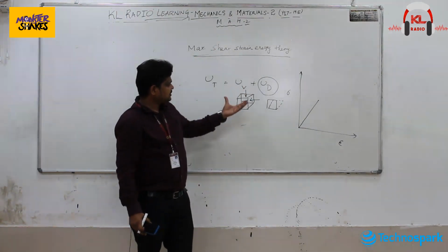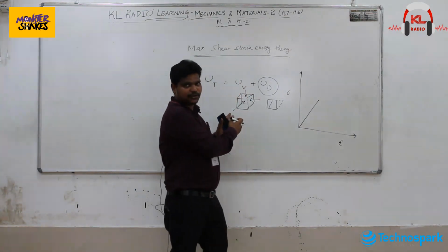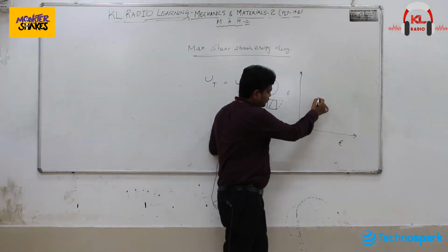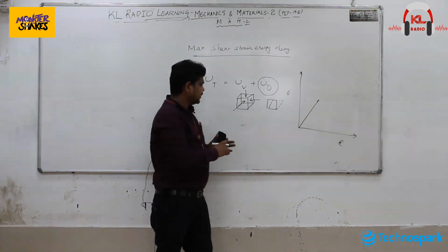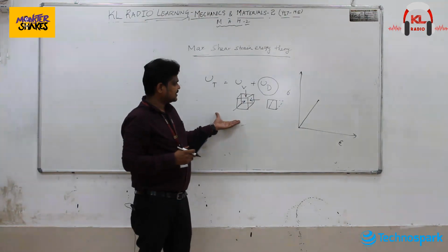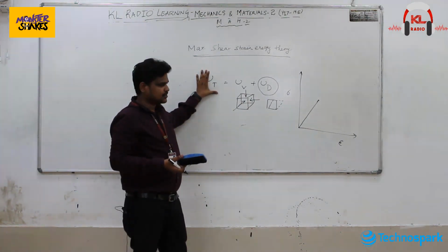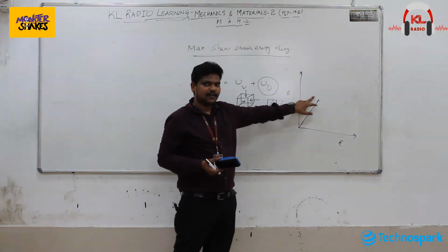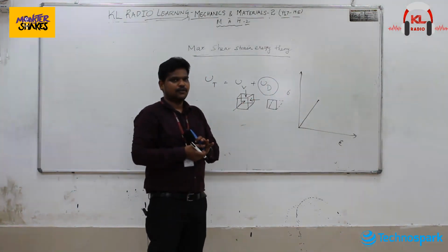So von Mises says that the volumetric strain due to hydrostatic loading will usually occur in this region, up to the elastic point where it ends. Once it starts yielding, the material goes to distortion. So von Mises says that instead of calculating the total strain energy and comparing with the uniaxial case, calculate the strain energy which corresponds to the distortion, and that energy will be the exact energy for the failure.